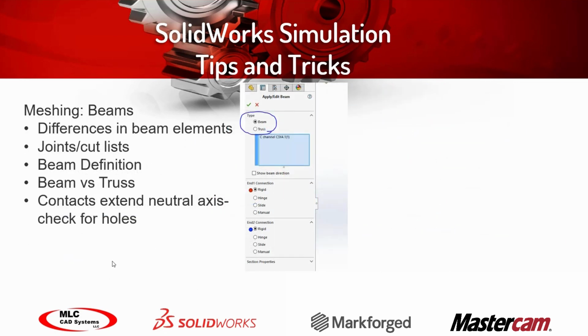Now, coming back to beams, there is a way that you can define that beam to only take an axial load. That's how we define it as a truss. Otherwise, by default, it'll just come in as a beam. The joints can be edited, and those are essentially the calculation points. Beams are pretty straightforward. Most likely they're all going to be bonded anyway, but make sure that if you have a truss or an only axial load member, that you define it so in the beam definition.